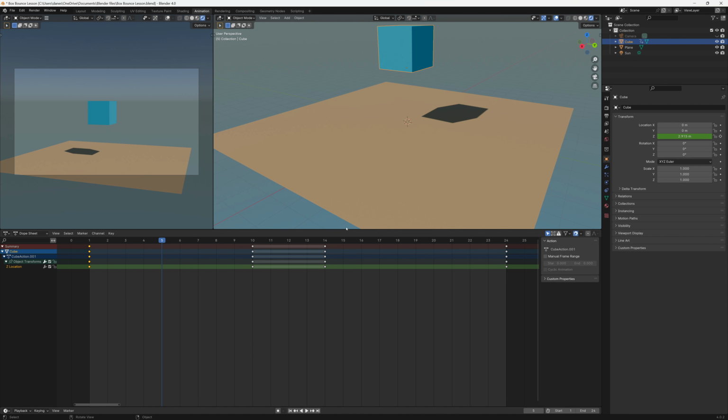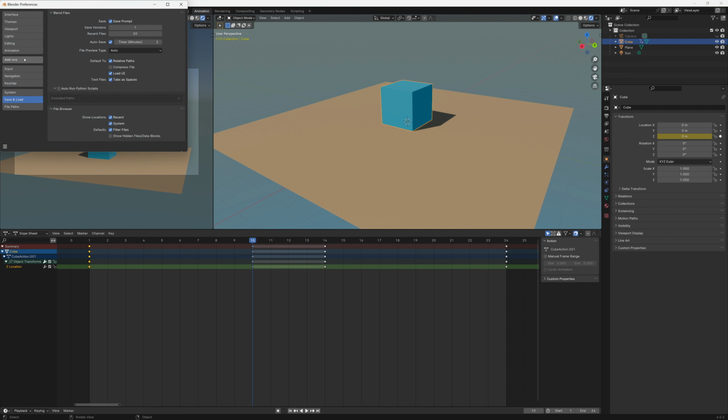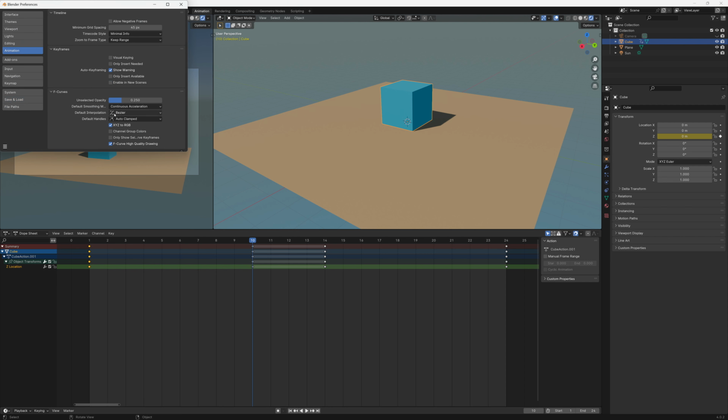So we can't fix that in the dope sheet without doing step animation, where we actually manually add animations going every frame like so, kind of like your stop motion animation. Okay, remember we talked about before that there is a default animation interpolation here, a behavior. So you can change this behavior to constant if you want it like that. You see it where it looks like it's a step.